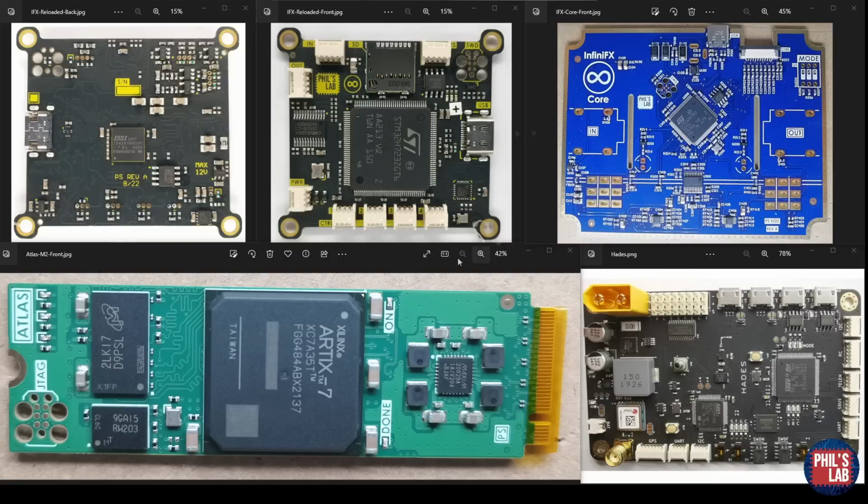The boards you're seeing here were all manufactured and assembled by PCBWay, and I went through the exact process you'll see in this video to generate the relevant manufacturing and assembly files. As you can see, some of them have through-hole parts, most of them are SMT parts, double-sided assembly, so components on the top, components on the bottom, as well as customized stack-ups because I had several controlled impedance requirements for some of these boards. I'd like to show you all this information as it can be rather daunting if you haven't done this before, but to make sure all your assembly and manufacturing processes go smoothly, it's very important that you take care with this design step. Without further ado, let's get started.